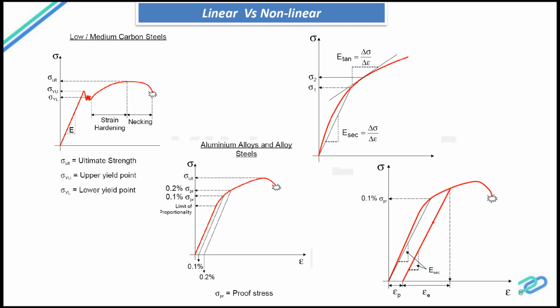it's very complicated. So for these cases in the engineering community, even within Patran and Nastran, instead of Young's modulus, we use the tangent modulus or the secant modulus. For the regions closer to the proportional limit of the material, we can try to idealize or assume it falls within the elastic region.